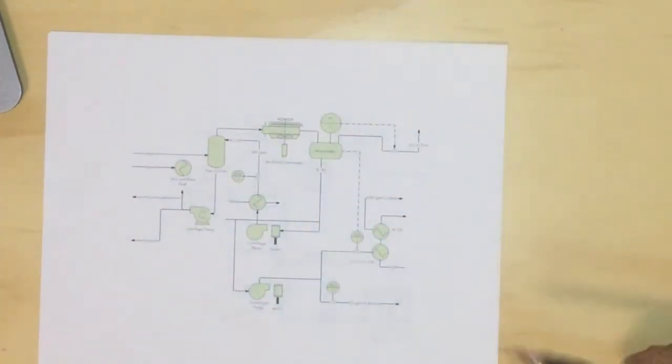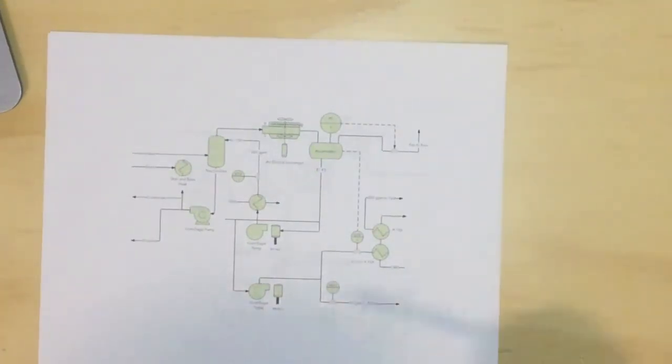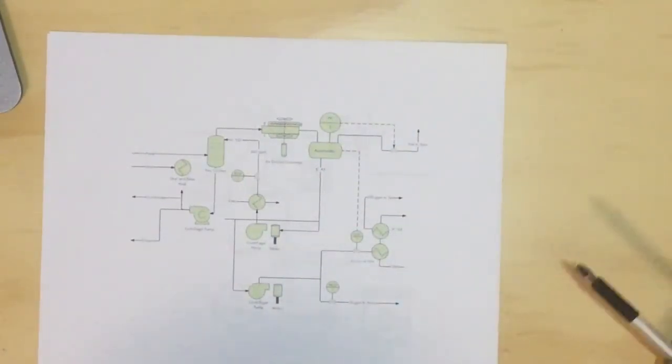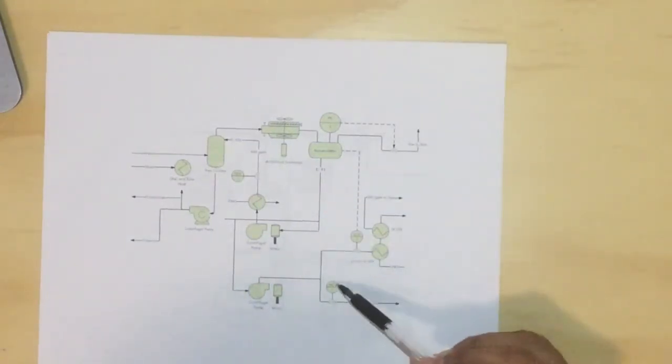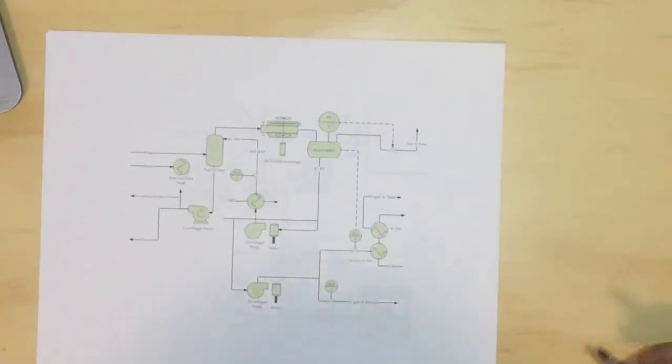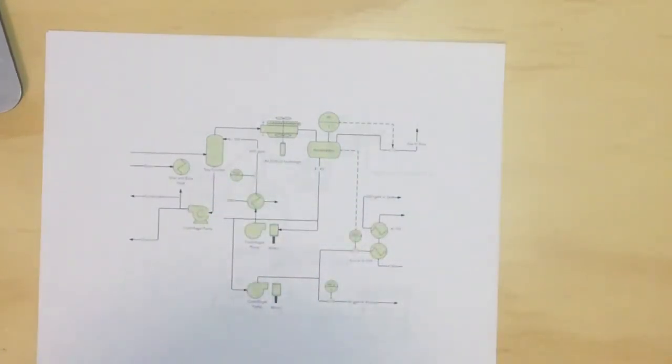These symbols are important because there are different kinds, and the most commonly used are the analyzers that have an A. This has a P that is for pressure, there are L's that are for level, and there are T's for temperature. Here we have other letters like H and F, and depending on where they are located, they are the tasks that are accomplished. H is for a hand switch, here is a bulb, and F is for another task.